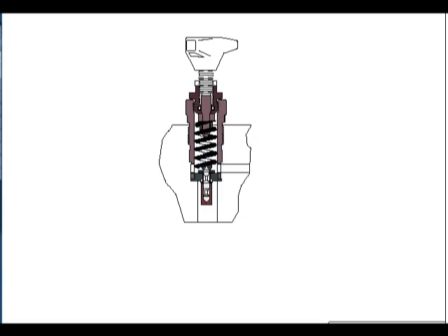It should be noted that direct-acting relief valves are usually available in only relatively small sizes because it is difficult to design a strong enough spring to keep the poppet closed at high pressure and high flow.